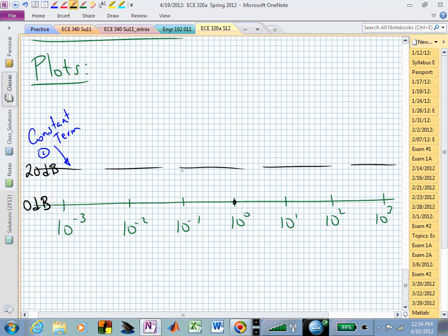Meaning if I do this correctly, it should be at plus 20 dB before that, and minus 20 dB above that, and everywhere else it's at that same slope. Really you should be getting out your ruler and making these sketches much more accurately than I am. But that is due to piece number 2.